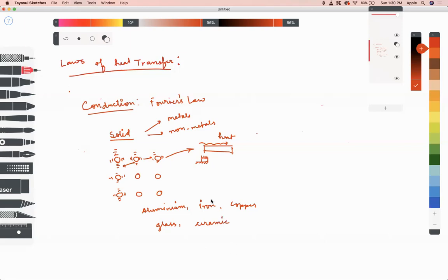All right. So what exactly changes between these two? Why is one good and one bad? Because both are solid, correct? And vibration is taking place in both of them. So this is where we have to really look into what percentage of heat transfer is taking place with respect to vibration. If we go for a definition of conduction, it happens because of exchange of energy between molecules, all right, due to lattice vibration. This is called your lattice vibration.